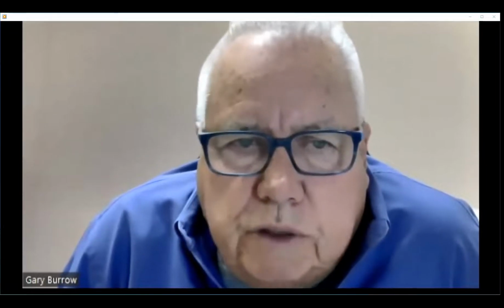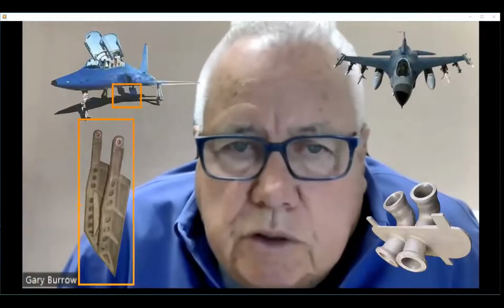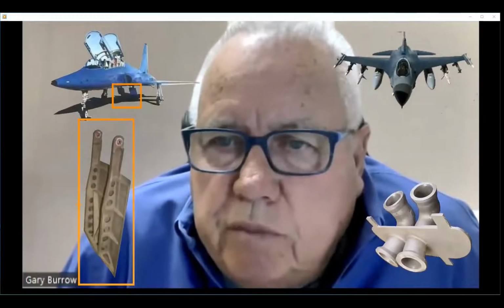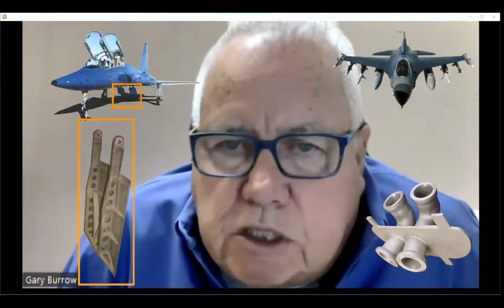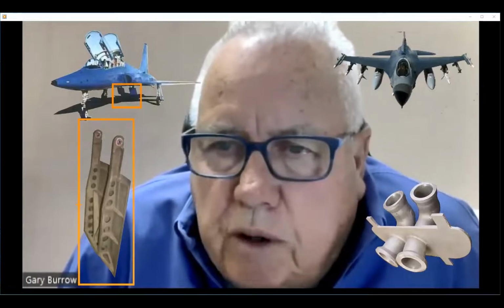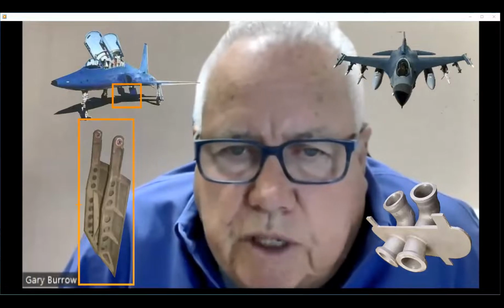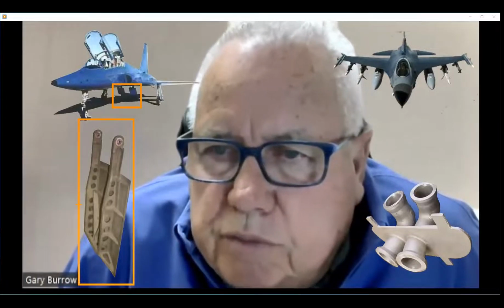These are the elements that I do every day in the development of the 3D solid models, using additive and subtractive manufacturing technologies to build mold tooling or mold cavity elements in collaboration with metal caster and machine shop partners. Several times in the past, I have made DLA legacy castings in airset sand, taking responsibility for the whole project when other metal casters and or machine shops had failed and their contracts were canceled.